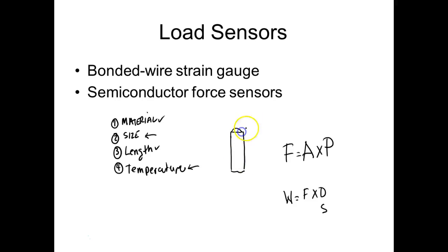And then the actual weigh bridge would ride on top of this thing. And when that truck pulled up on that thing, guess what that metal actually did? It would actually decrease in size this way, and it would increase in size that way. You couldn't see it, but this is the way these things work. The load cells themselves had big chunks of metal in them, and when these trucks pulled on top of that, it would squash that thing down.